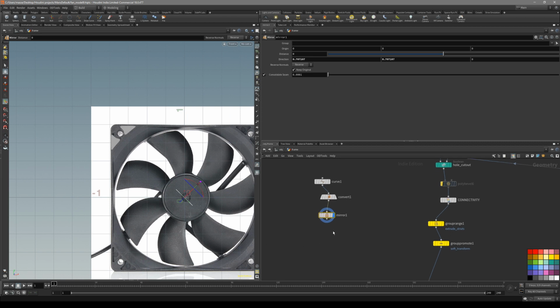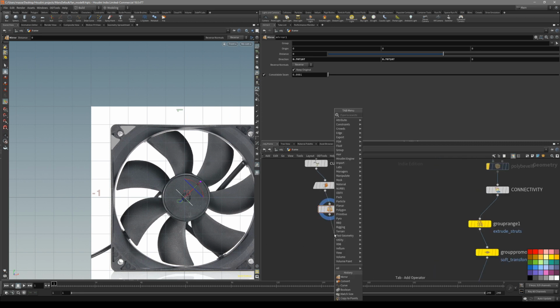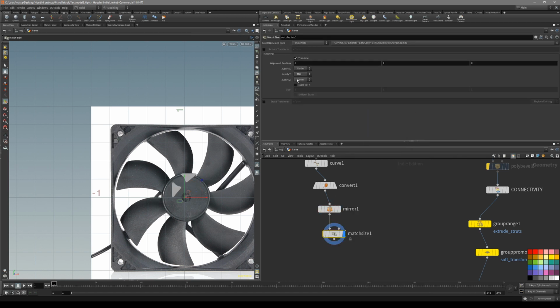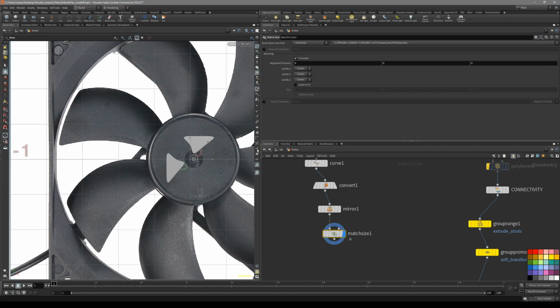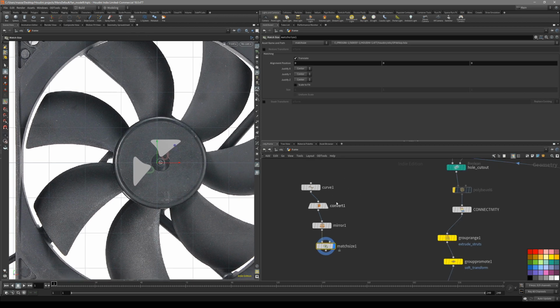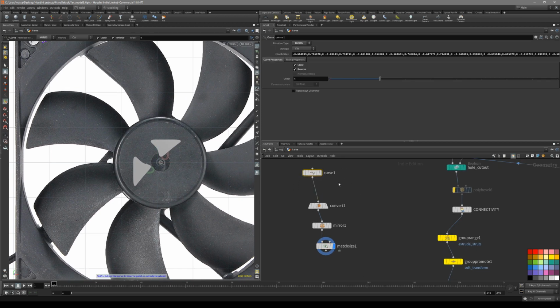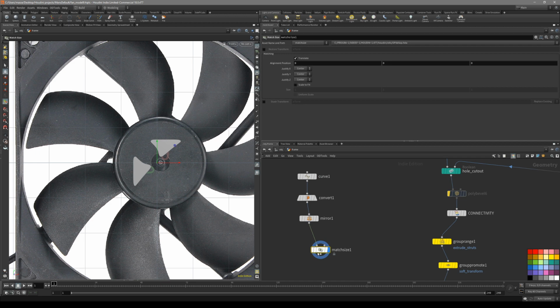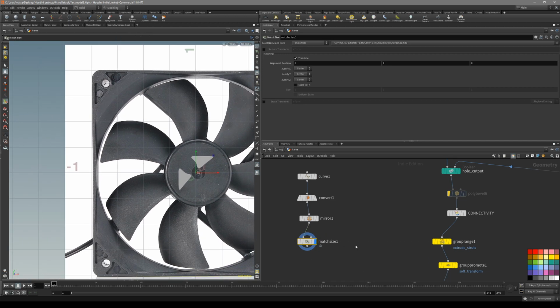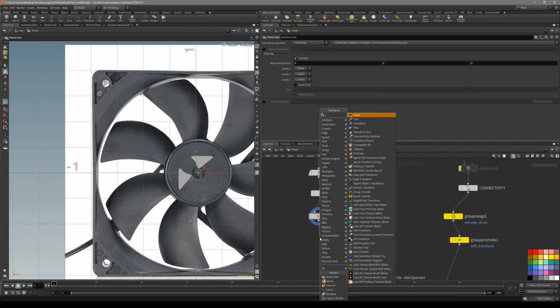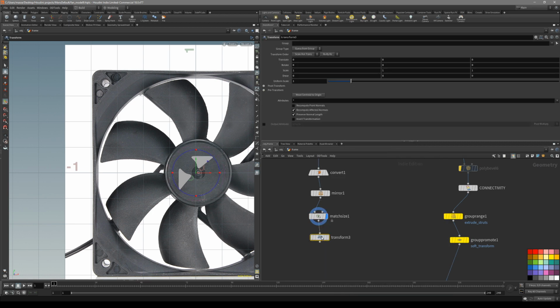What's good about this is we now can put down match size and put all of these right at the center. What this does is it basically uses the base position for all of our booleans. So even if we create another shape, they all are going to be at the center of the centroid, so we can always know the position, and then if you want, which you'll need, we can transform it to the right position with another node.